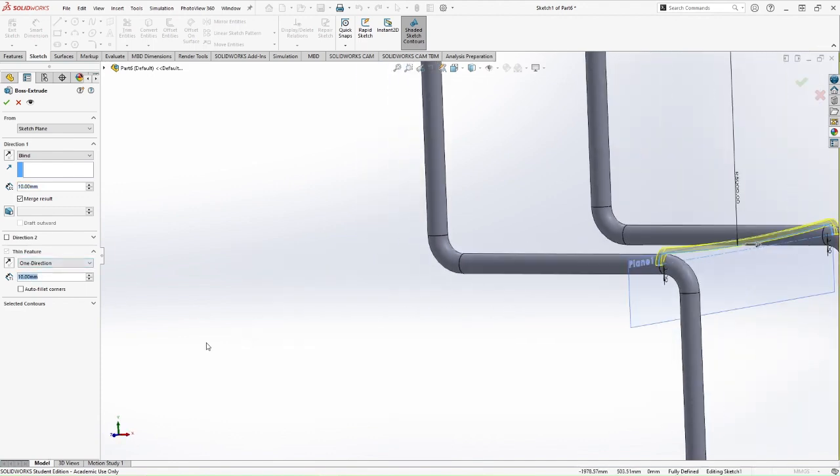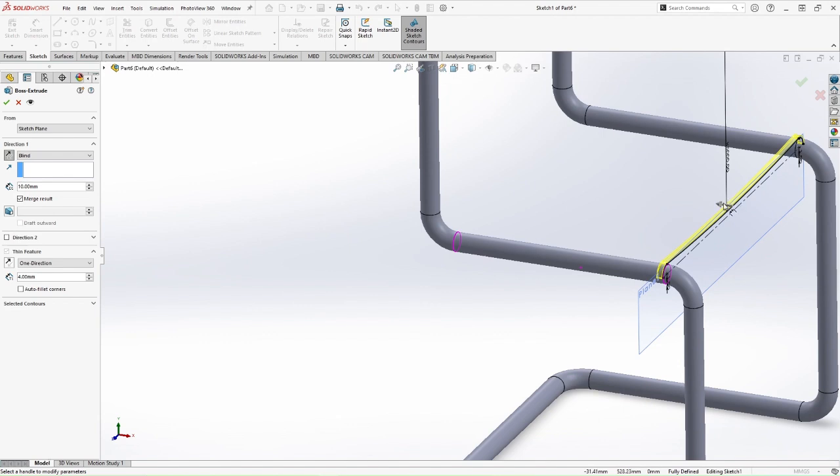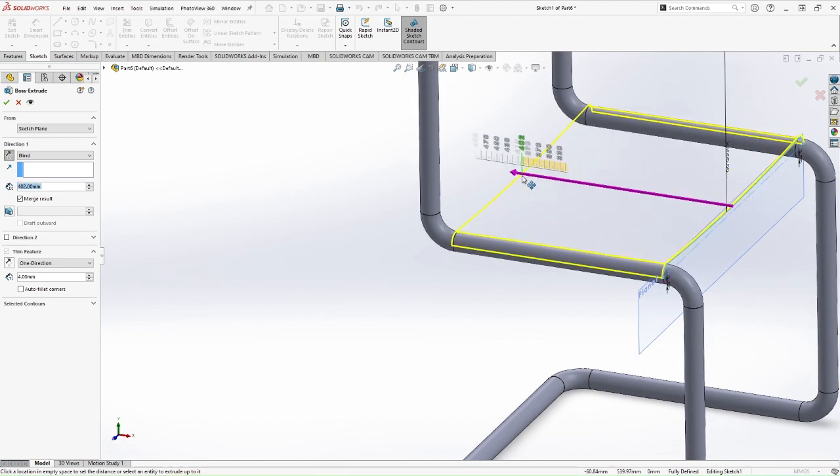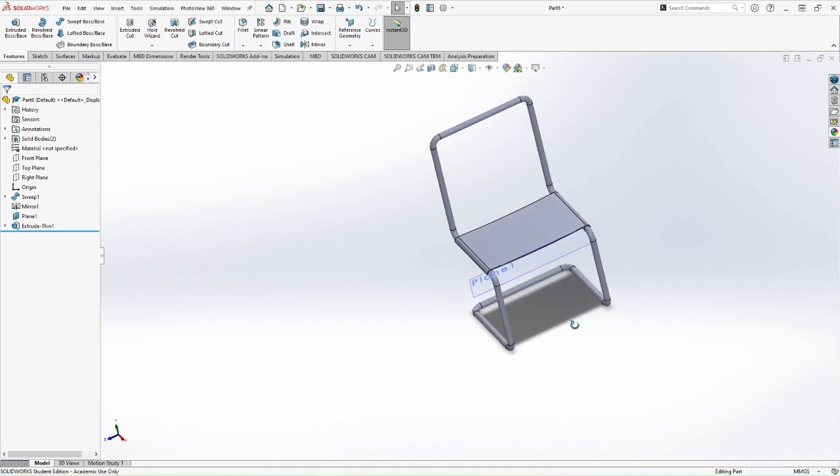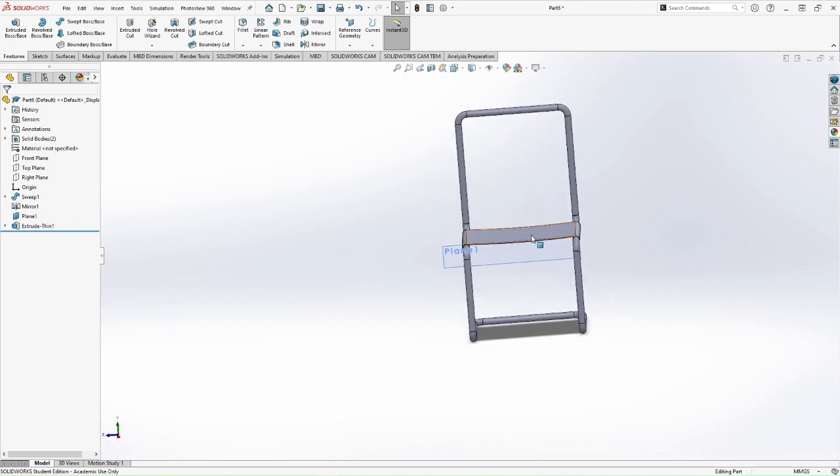So that's going to be 3 millimeter thickness or 4 millimeter thickness, and let's change the direction to going into that way, and this is around 400 I think. So I'll change to enter 400, enter, and click OK. Same thing you will do for the seating. If you feel that this is too small or big, you can make the adjustment using these dimensions.